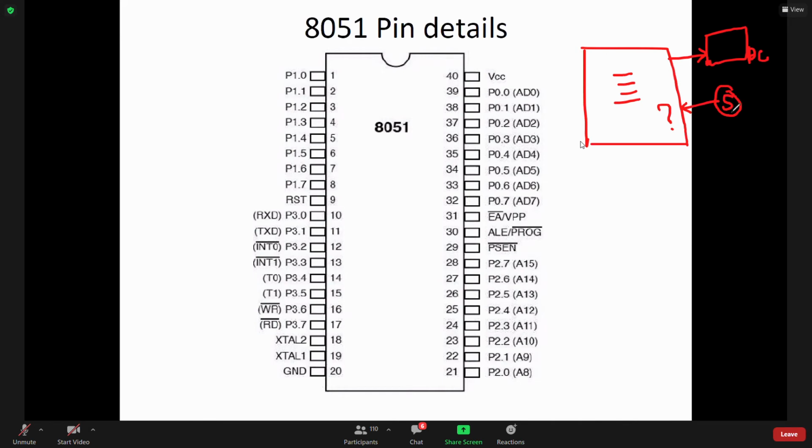So I will search for a pin where I have to connect this sensor, and obviously I know I have to use an ADC pin only. On the microcontroller, I will search how many ADC pins are available. Assume there are 4 ADC pins available. I will decide on one of them to connect the sensor. I will worry about this pin only, and not any other pins in the microcontroller.